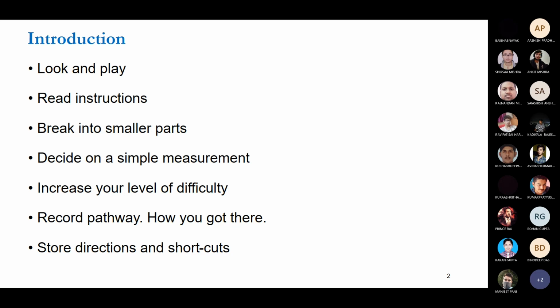Also you are able to amplify the ranges, meaning gain factors are another important feature of the oscilloscope. There are different gains, so as per your measuring procedure you can step up or step down that value. By stepping up and stepping down, we are able to accommodate all the signal in the window of your oscilloscope. These are the other features: you are able to measure and visualize the value.